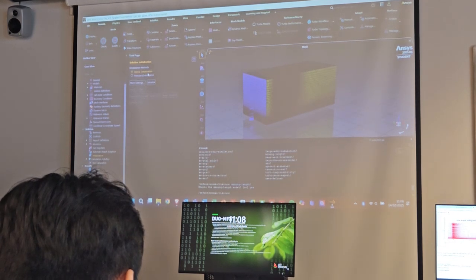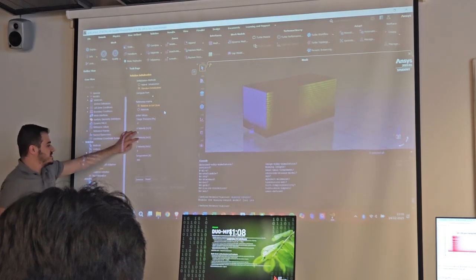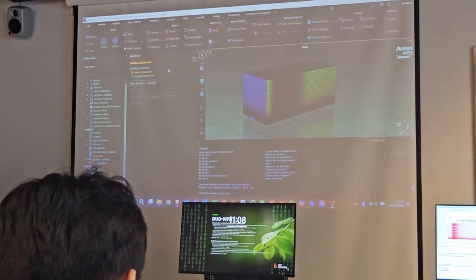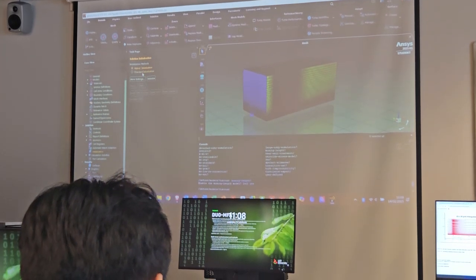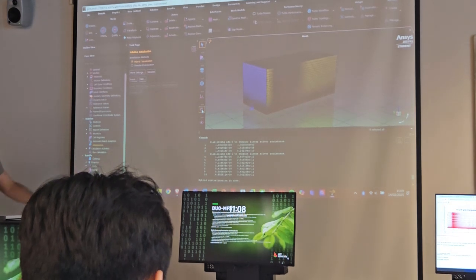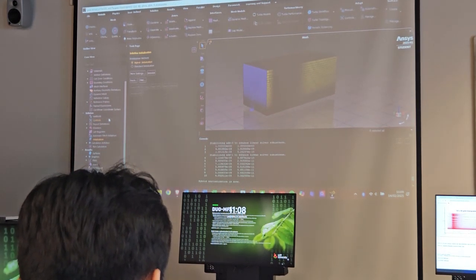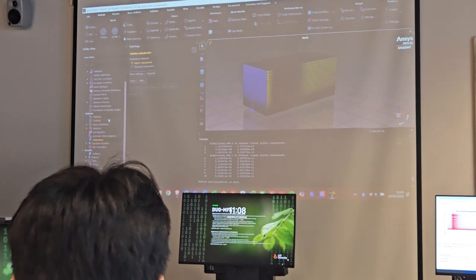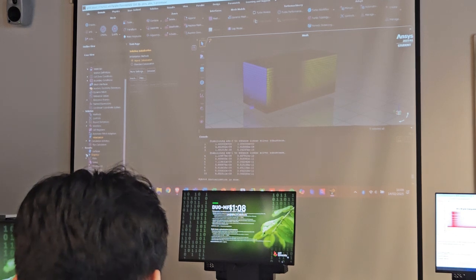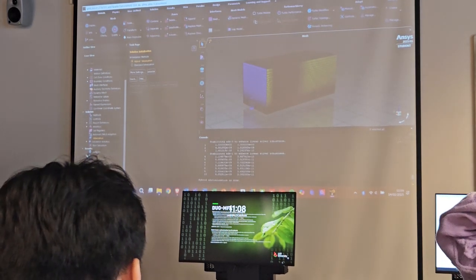Or a standard way to initialize it, where you can actually set the pressure, velocity, and temperature in the domain. We are fine with the hybrid. We don't need to check what's happening. We can just let it happen, and if I hit initialize, then you can see there is some iterations. Sometimes this works fine, sometimes no. So we can check if this worked fine. So now we already initialized the domain, so we have flow variables in the domain, and we can plot them.